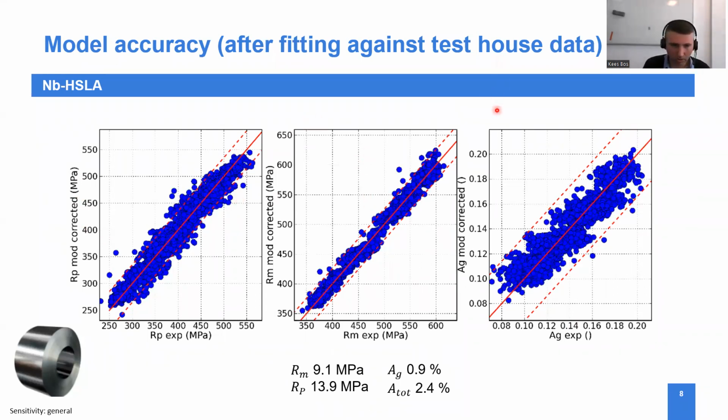You can imagine that at the steel plant, like in Muiden, we generate lots of tensile test results. So this is nice data you can use for that purpose. And it turns out that the tensile strength, for example, you can predict quite reasonably accurately within a standard deviation of around 9 megapascal, which for many purposes is really good enough. Of course, then you might ask, well, how representative is a test that you take typically either at the tail or the head of a coil?